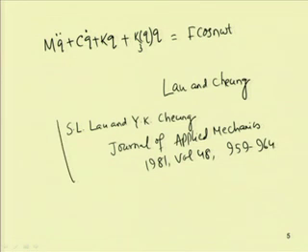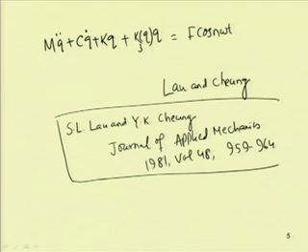According to the incremental harmonic balance method, this is a two-step method. In the first step we use an increment of the variables, and in the second step we use the Galerkin method to find a set of algebraic equations, which we can solve using the Newton-Raphson method or any iterative method.